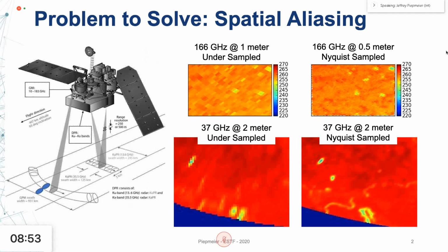atmosphere. And there's an interesting and challenging engineering problem on how to maximize spatial resolution, which turns into aperture size, while optimizing beam efficiency and spatial sampling, while trying to operate in multiple bands over nearly a decade of frequency, say from 10 to 100 gigahertz. And what happens is that this optimization usually leads to accepting edge-to-edge 3D contour sampling, as seen on the left.